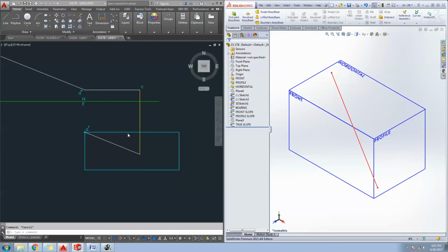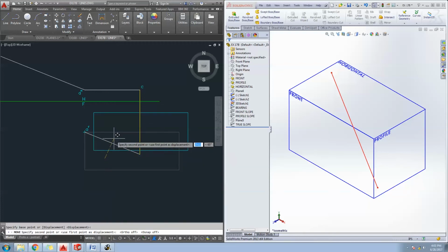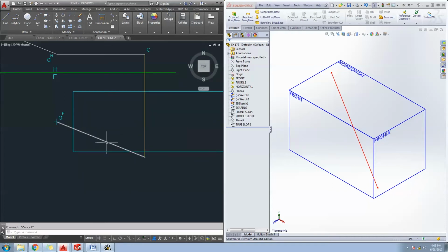We have to do the same thing in descriptive geometry as well. The quickest way to do that is we're going to pick up the triangle, we're going to move it, and we're just kind of going to drop it right about there, and then we're going to trim away the excess. Good. Now we're going to add some text to that. We went over 100 units, and we went down 40.